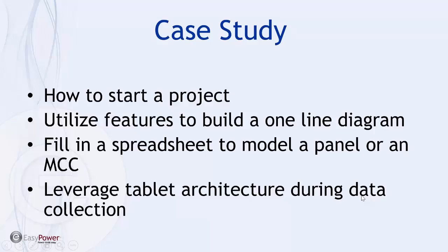So now, at a bare minimum, there's a certain amount of data that's required for short circuit and arc flash, and those forms are built into the on-site defaults. But by adding a few more equipment details, which can be done in notes and can be done in the templates by modifying the templates themselves, we can actually expand the capabilities and the value added of doing the data collection by incorporating this additional information in terms of asset organization, tracking, maintenance files, and the like.